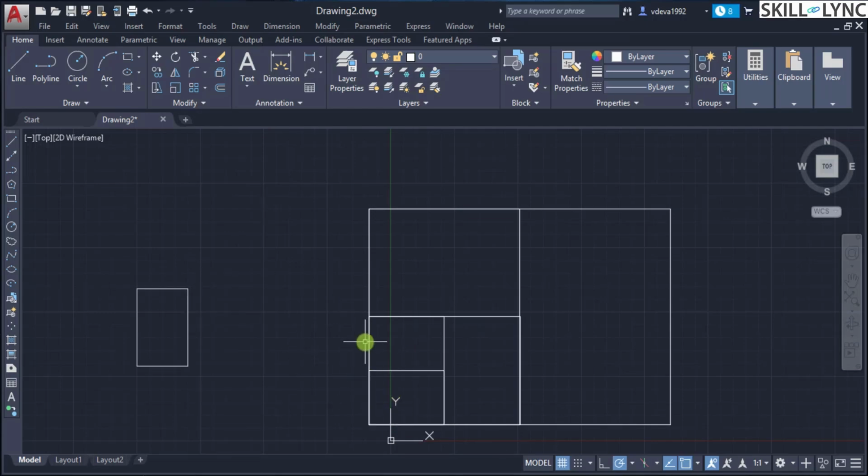At max you can maybe try and squeeze it into your A3, but remember you have to place your annotations, the dimensions, the title sections and all that information into your page. So based on your paper size is where you have to determine the drawing that you are using. Suppose if you want to position this object into your A4 size itself, within those limits, then you have to apply your scale command that we'll be looking into later.